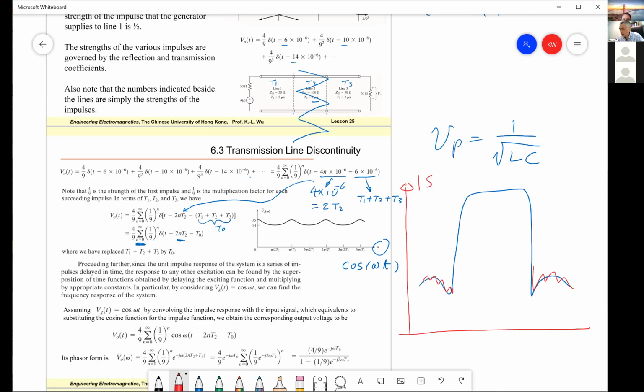Say this is the transmission coefficient. When this is say 30 dB low, when the signal is very weak, you can see the ripple because the reflection is a very small amount, but superposed on your signal, you see the ripple. So in future, when you do the measurement in frequency and you see the ripple, very likely you have a multiple reflection happening inside.